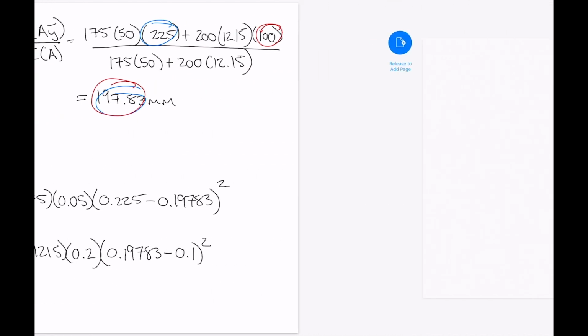So let's flip back here and say that for the steel, our safety factor is given by the yield strength of the steel divided by the maximum stress in the steel, which is the yield strength in the steel, divided by My over I transformed, right?